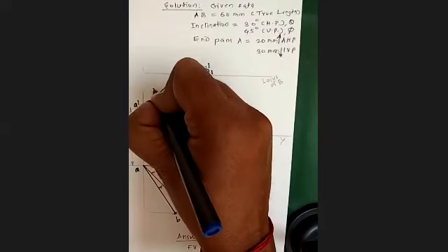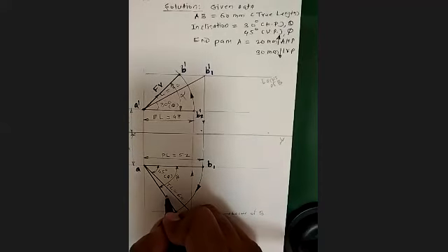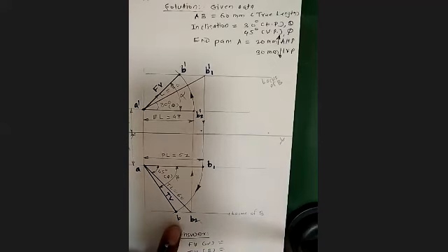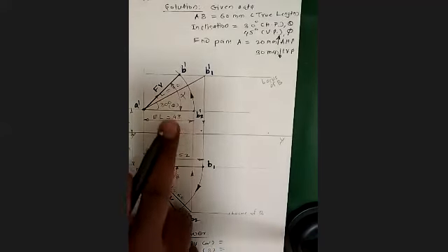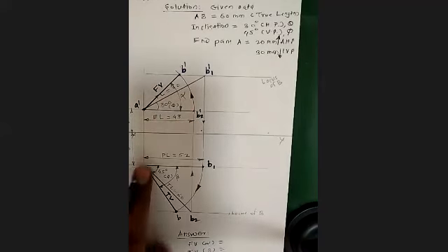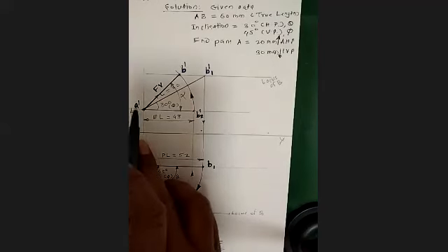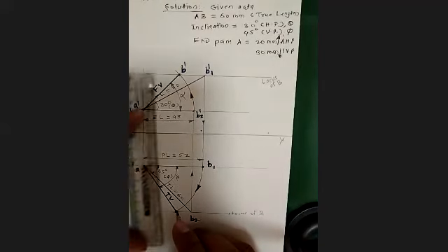This is the front view. This is going to be the top view. This line AB is your top view, angle beta. This is A dash B dash, your front view, angle alpha. This is the elevation length EL, plan length, and one more important point we have to add here. A dash A is one projector. Similarly, you have another point, B to B dash.